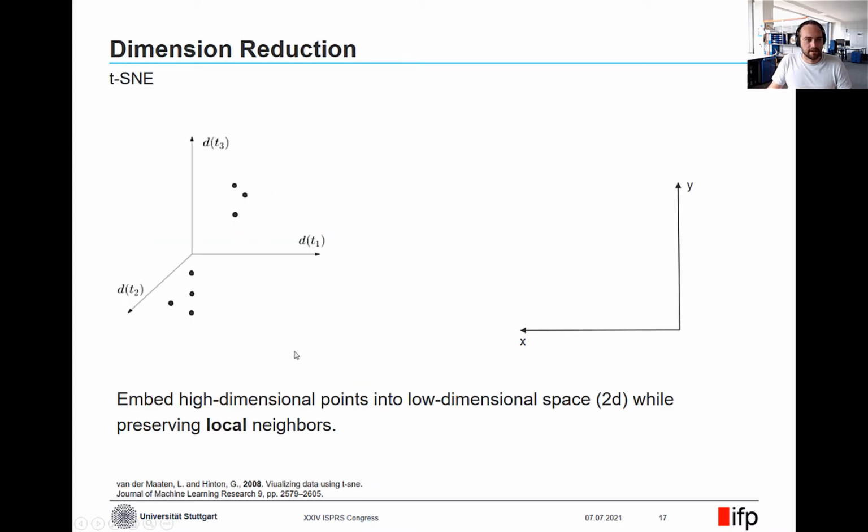So clustering in these 132 dimensions is quite unreliable and comes with various curse of dimensionality problems. Therefore, we use a t-distributed stochastic neighborhood embedding, TSNE, and the previously mentioned distance metric to embed this high-dimensional space into a 2-dimensional space while preserving the local neighborhood. So we go from this high-dimensional deformation space into a 2-dimensional space where the points have the same neighbors they had in the high-dimensional space.